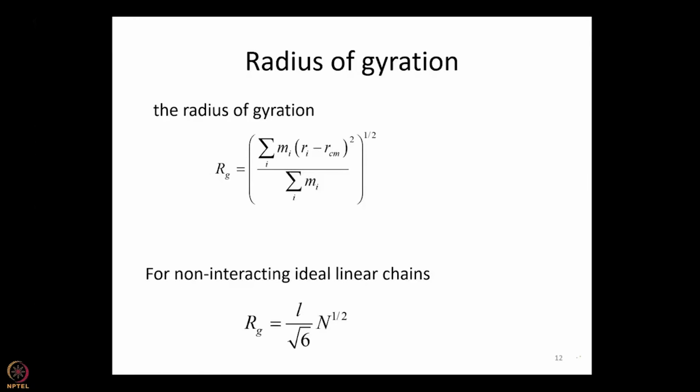So as I told you before, radius of gyration, which gives a good measure of the size of the polymer, and the mean square end-to-end distance, they are essentially the same thing. And as to the numbers, as I told you already, a polymer is millions and millions of monomers. That means n is upward of 10 to the power 7, say, or 10 to the power 8.